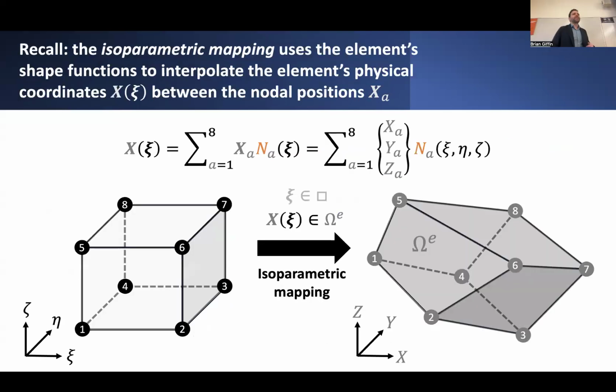But we'd actually already talked a little bit about how we address some of these issues. We started talking about this when we introduced this concept of the isoparametric mapping, or the isoparametric transformation, which said that any element that we choose to represent, let's say, maybe this kind of 8-node distorted hexahedral element that has nodes arbitrarily positioned and skewed in some configuration, we can nonetheless relate this element back to some corresponding parametric configuration that is itself a perfect cube with bi-unit dimensions. So a length of 2 on each one of these different sides.